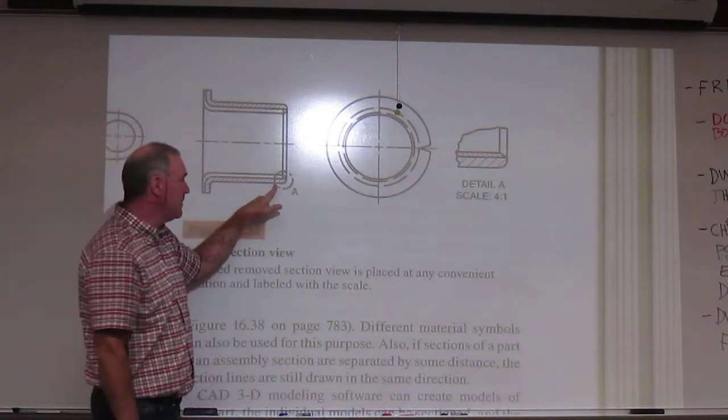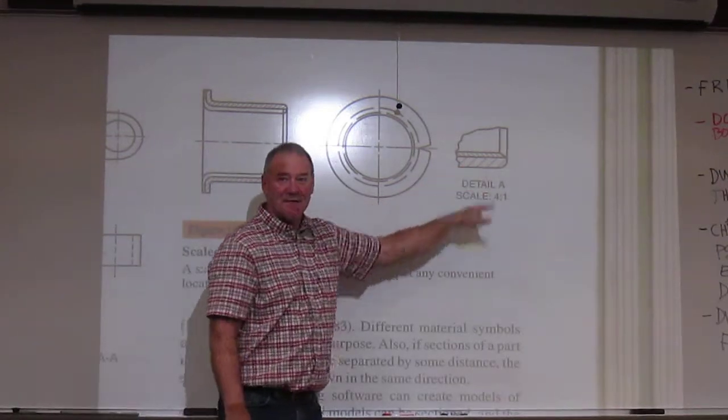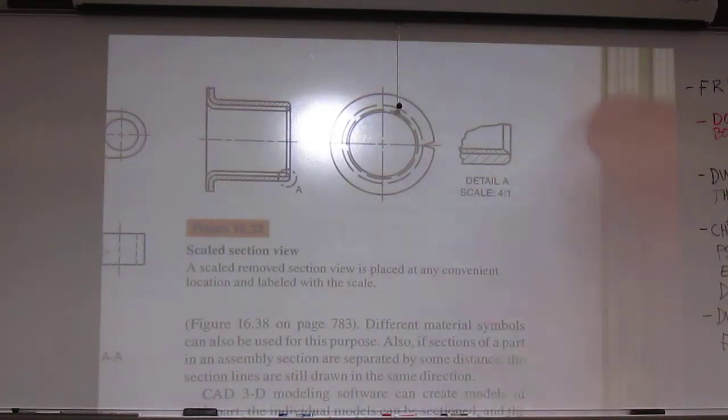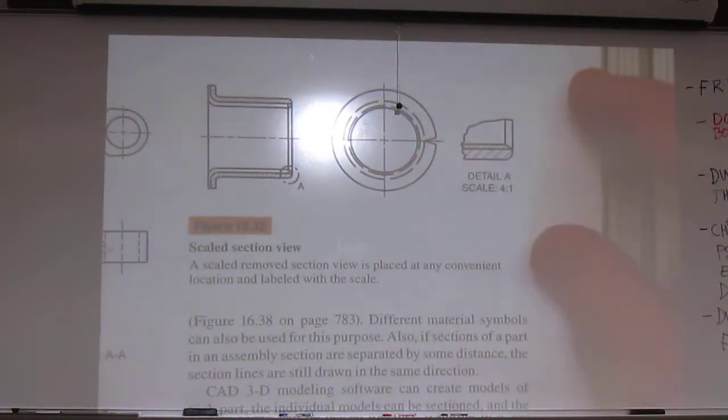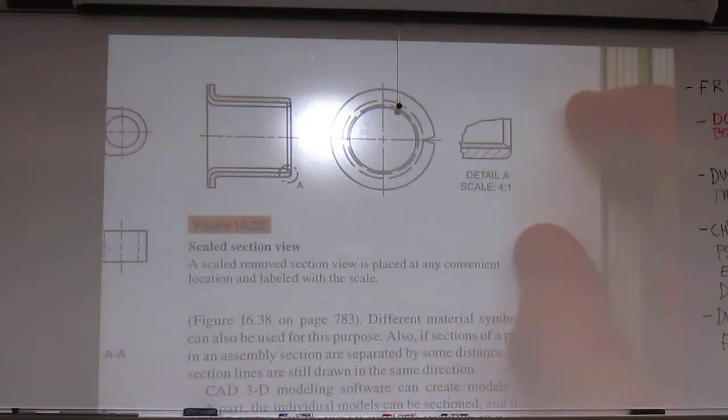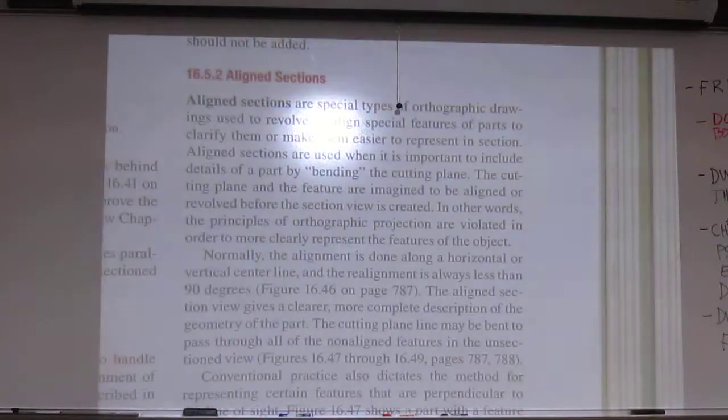We're just taking that shape, we're going to bring it out, but we are going to section it. And that's really technically the same thing as the other one, but here we are not rotating the object 90 degrees, like that little biology slice that you would put on a slide. Okay, that's the removed section. This one is probably your most widely used one, other than the full section. We use this a lot. Pretty powerful little descriptive device.